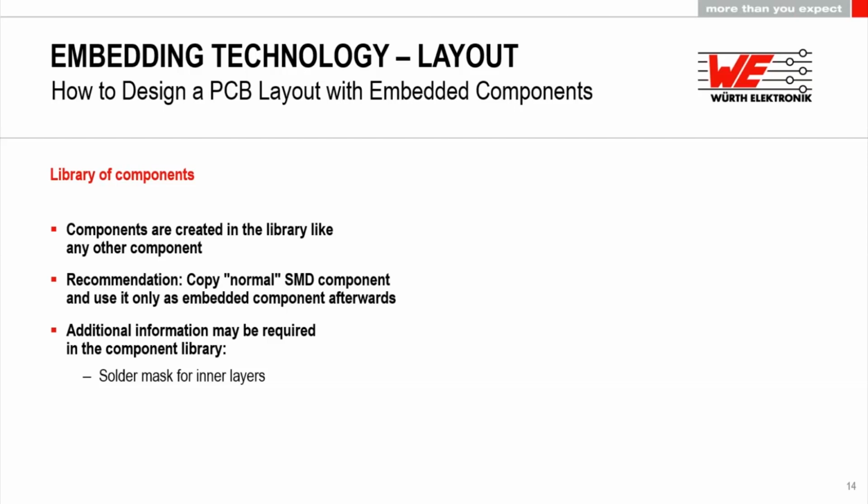As far as I know, none of the mentioned 5 tools is yet capable of creating an automated inner layer solder mask and inner layer paste data. So you need to have additional information here, and how you do this I will show later. And I would require a specific component outline.